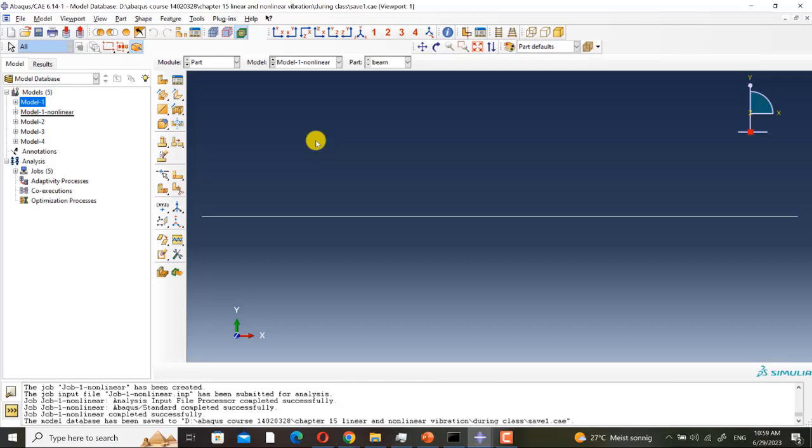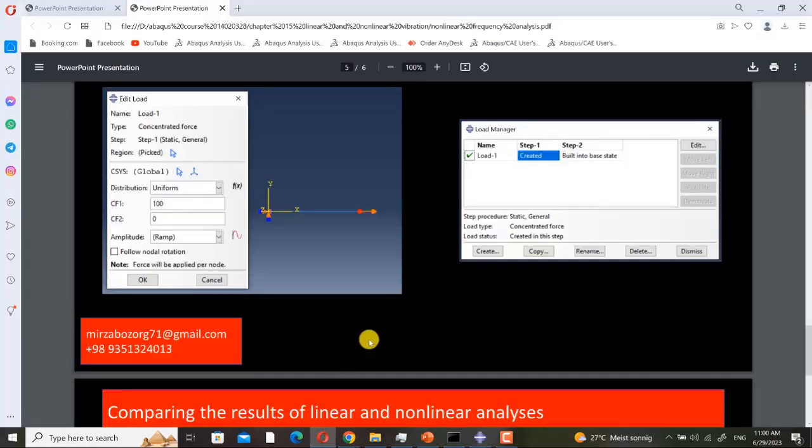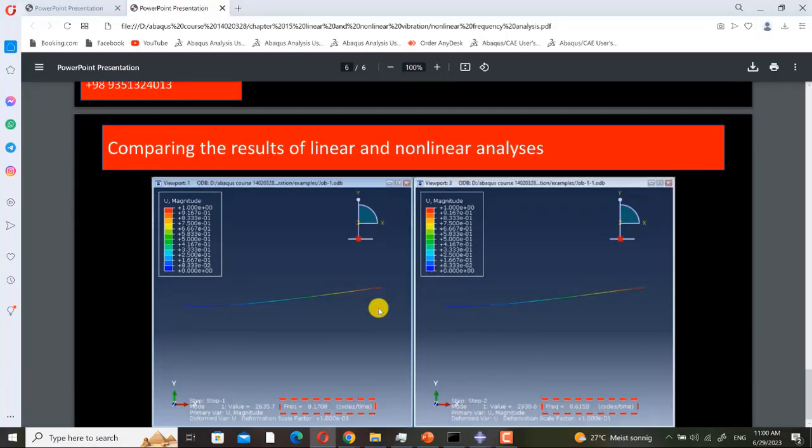I have forgotten what it was in Abaqus. I told you in chapter 9 in the bolt connection analysis. And then in the third step, you must define a frequency step, and then you can do the nonlinear frequency analysis. That was the concept of it. As you can see, it is very easy.